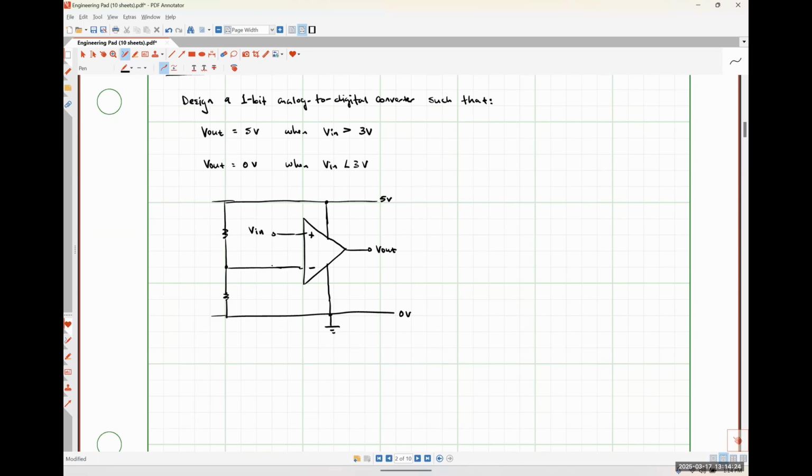So to be clear, essentially what we're doing, I'll do it over here in blue because this is technically an aside, is we've got 5 volts up here. We have some resistor R1, some resistor R2, and we want the voltage at this node, which is the same thing as the voltage drop across resistor R2, to be 3 volts. And we're trying to decide what R1 and R2 should be.